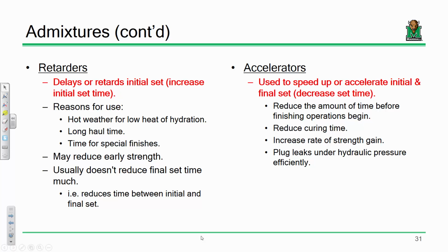Now, if you use a retarder, that's great. You need to make sure you're aware of a couple things. It might reduce your early strength. So depending upon your application, that might be a no-no. It's just something to think about. Everybody good so far? Any questions? Okay.